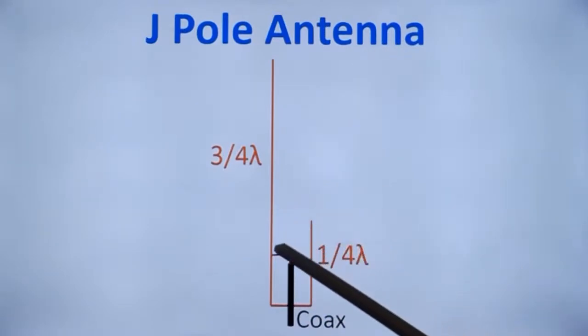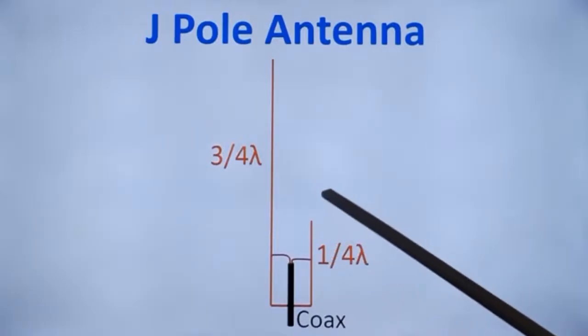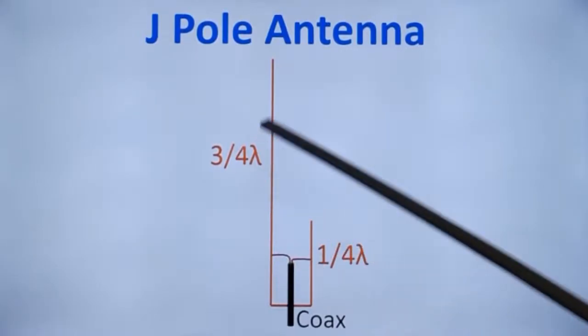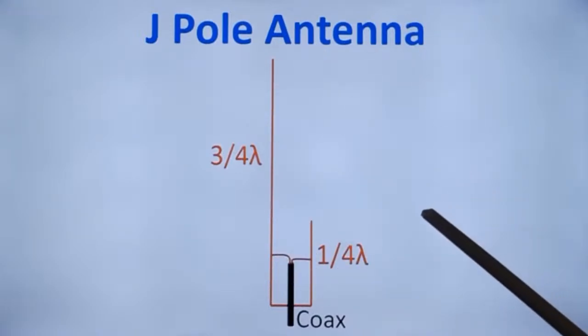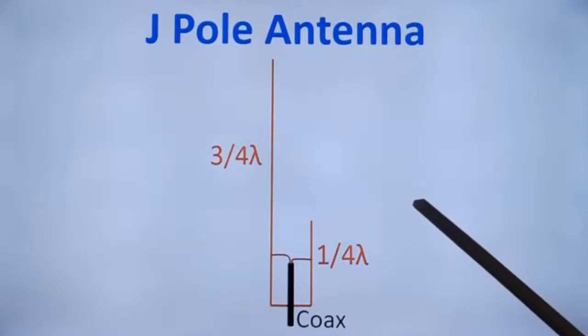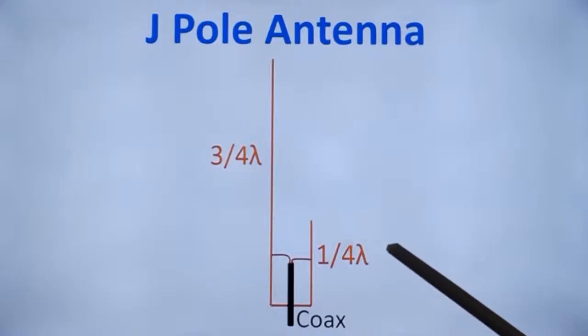And the J-pole antenna has a little higher gain in the direction of the quarter wave matching stub. This antenna has been used for terrestrial communication through repeaters and simplex operations, as well as for satellite communications. In satellite communications, the usual amateur band for UHF, ultra high frequency, is on the 3rd harmonic of our VHF band.